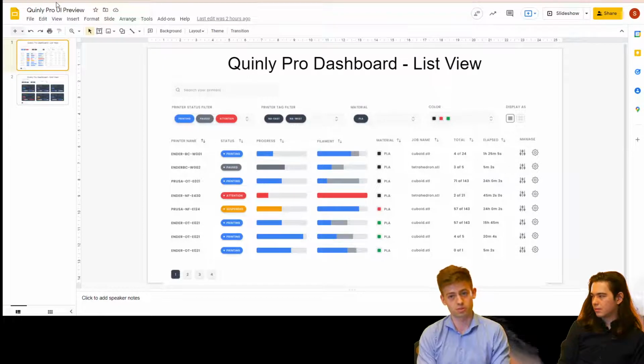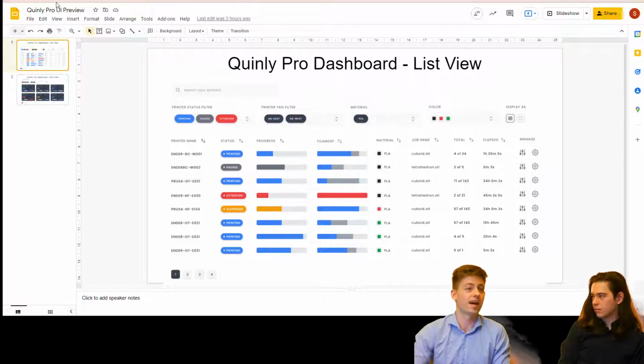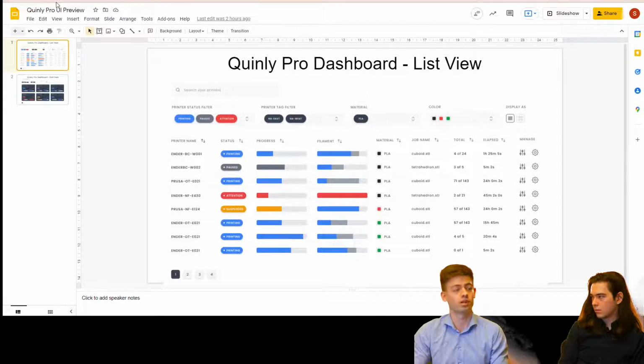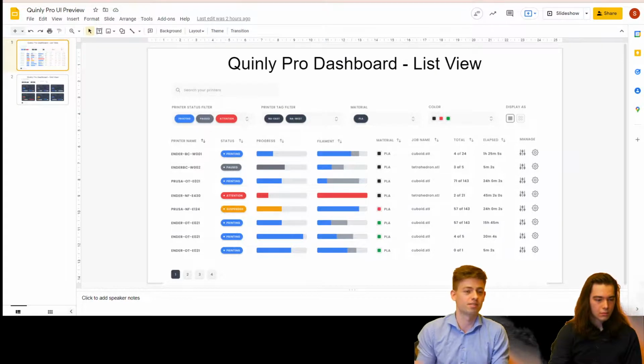So I would probably do a file name thing where I have Benchy brass nozzle G-code, and then Benchy steel nozzle G-code. It'd be actually like Benchy PLA 0.4 brass, Benchy PLA 0.4 steel, and if I had to change it to PETG, I would make a whole new G-code, Benchy PETG 0.4 steel. And the only thing I would change to print with PETG is the bed and nozzle temperature.